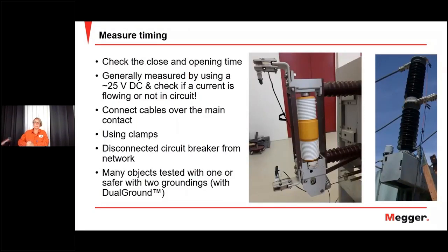Okay, timing, it's the same thing there. Look for the figures in the manufacturer's specifications. If you don't have anything, compare, not only within the different phases, but also similar types of circuit breakers. And the problem is here, you really need to have quite detailed figures. We come to that.